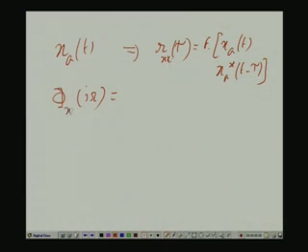So, similarly, here phi_xx(j omega), which we know is the Fourier transform of the autocorrelation function R_xx(tau), that is the integral of R_xx(tau) e to the power minus j omega tau d tau from minus infinity to infinity. We have seen that even though the random process is complex valued and therefore the correlation is a complex valued function, the power spectral density is a real valued function. Okay. And if the process is in fact real valued, then the power spectral density is not only real valued, it is also an even function. In fact, it is a non-negative function which we will show today.